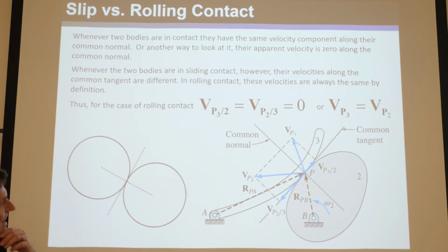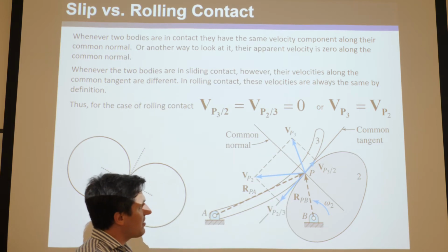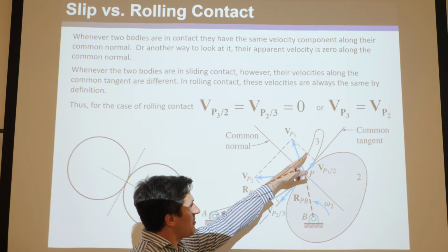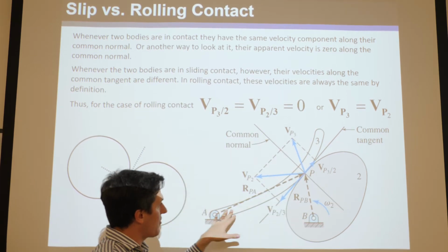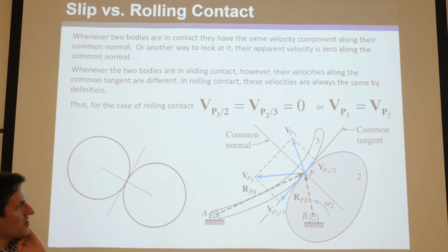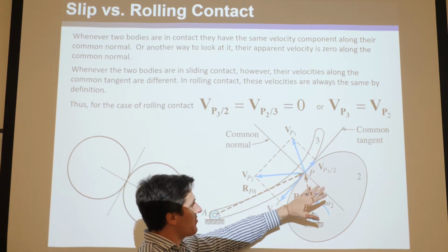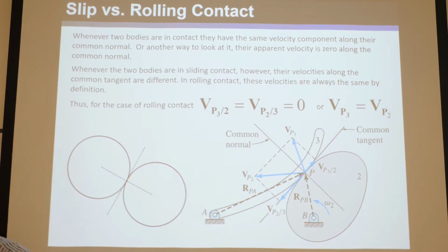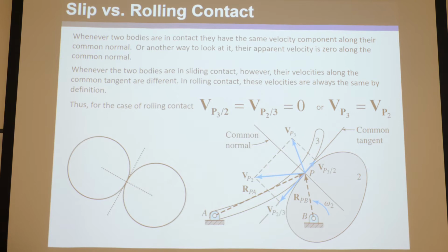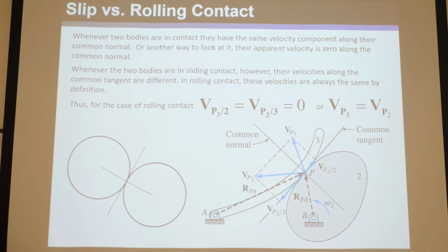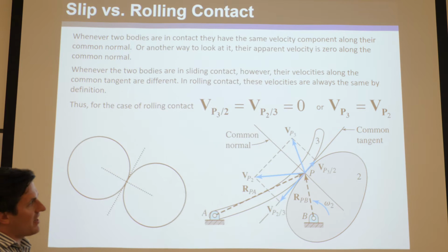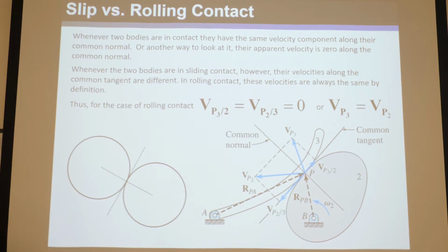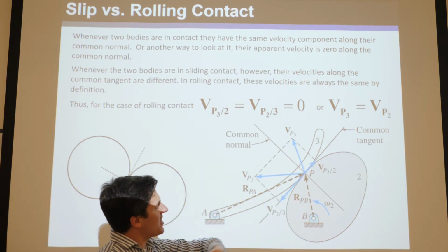What I basically just said, if you now think of this scenario here, we have this link of a weird shape. It's link 3 and this link 2, and then there's ground with pins here. Of course, for this to be a mechanism that moves and not a structure that's locked up, this has to have 2 degrees of freedom, sliding and rolling. And remember, just to review, this is a mechanism, but it's not a linkage, because there's a higher pair here. But anyway, that's not the point.